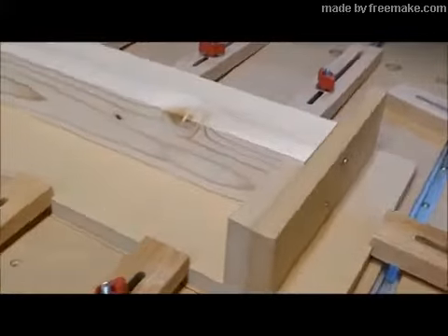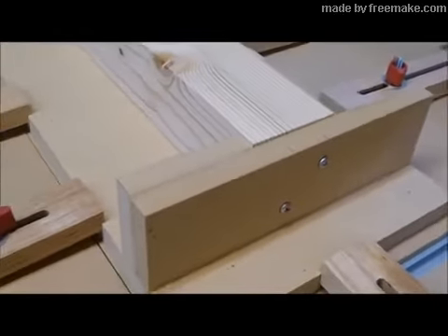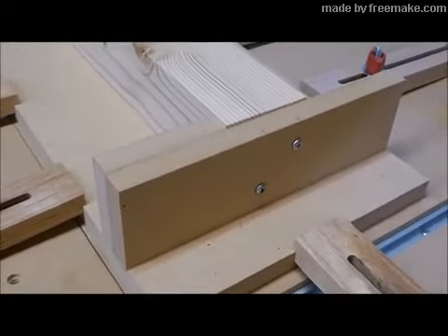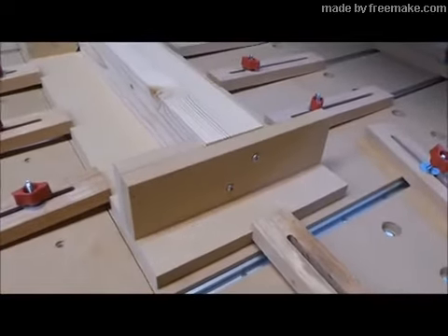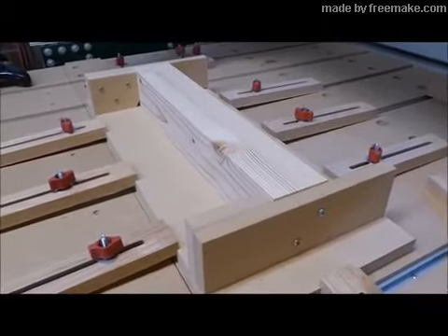The stock is registered to the bottom of the jig and against the 2 blocks attached to the uprights. This simple arrangement makes easy release of the stock, rotation of the stock, and then reattachment in a known fixed position relative to the machine coordinate system.